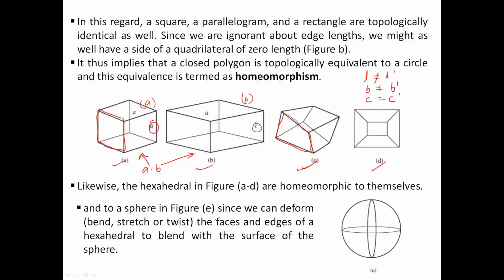No, they are not proportionally equivalent, because your length units are not similar. But are they topologically equivalent? Yes, sir. How? The adjacent position of the lines and edges is exactly the same. Or, in very simple terms, this face 1 is also a four-sided polygon, similar to face 1 of image A.